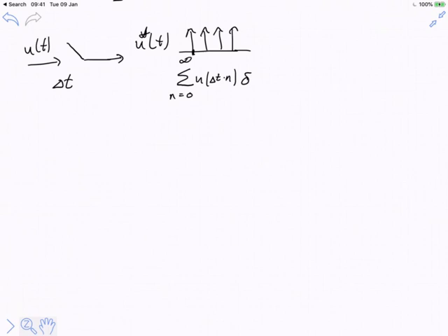But to get it to actually spike at that moment in time, I've got to shift it around. So I've got to translate it. And remember, I'm going to have to translate that by a certain amount of time. So effectively I'm delaying it. And so I want you to look at that with your Laplace eyes, and I want you to say, I understand how I would take the Laplace transform of such a thing. I know what the Laplace transform is of the Dirac delta, it's 1. I know how to handle shifts, time shifts, delays, dead time. It's just e to the minus dead time s.